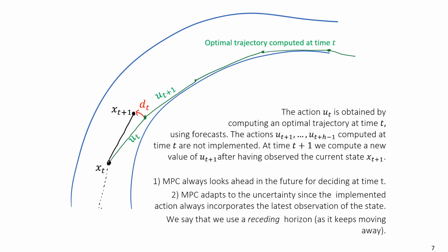When I drive my heating system, I know that the night will be coming, and at night, I know, for example, that the temperatures will be lower, and perhaps there will be periods of the night where the prices are higher. So I know those things, so I know where I want to steer my control actions, but at the same time, I don't do a control once for all into the entire future, because I know also that there will be differences, and I take care of those differences.